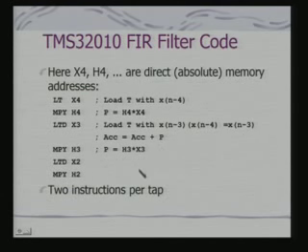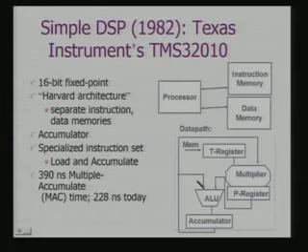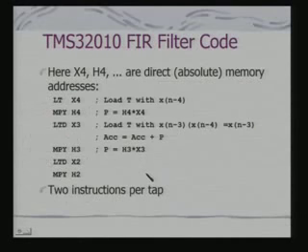So, effectively what I require is just two instructions per tap. This is possible because of the organization of the data path which has been provided. You can see that I can do the T register load as well as accumulation through the ALU to the accumulator simultaneously. So, you can understand therefore the demands of the processing and how it has influenced the design of signal processors.